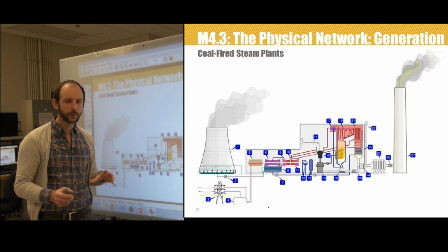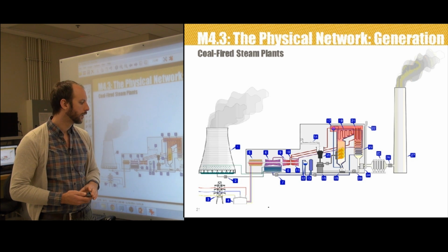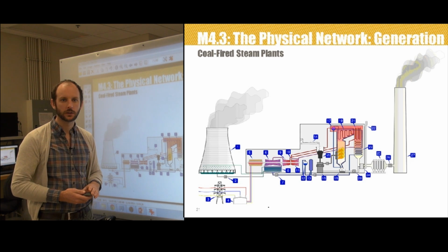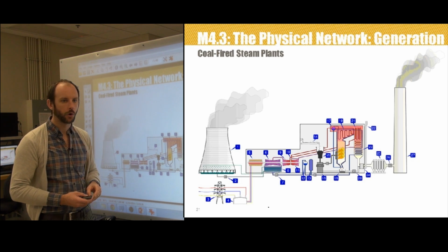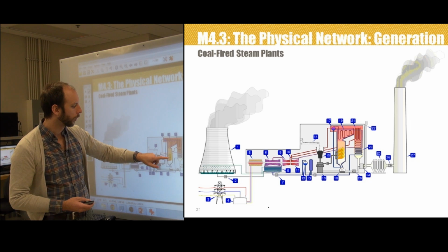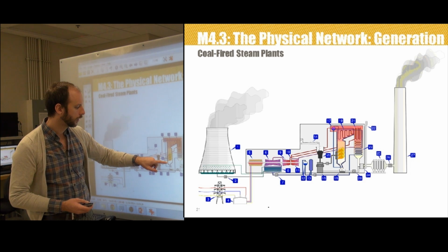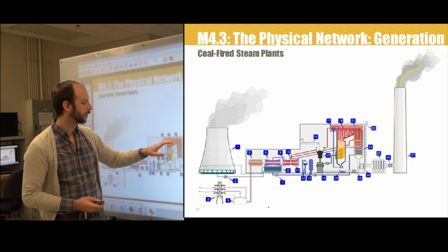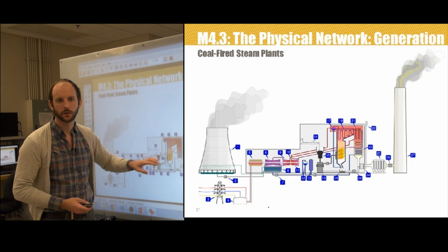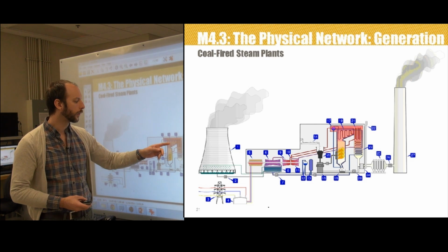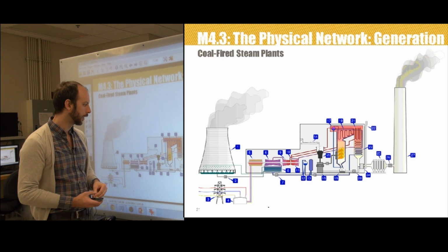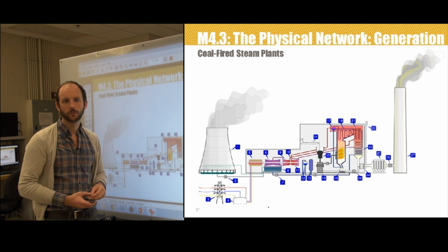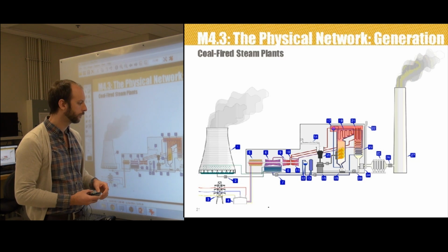Water of a very high purity, so it's very, very high resistance water, very clean water, is going to flow vertically up the tube-lined walls of this boiler system that we're showing in conglomeration here on the middle right side of the diagram. It's flowing through the walls of the boiler, so it turns into steam, and it passes through the boiler drum, where steam is separated from any remaining water.